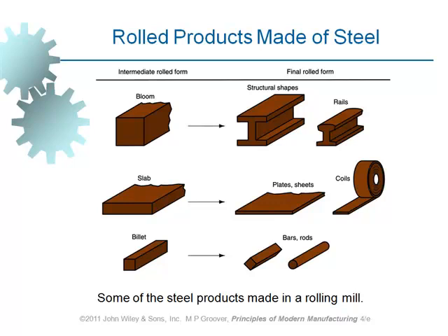At elevated temperature, we can alter the orientation of the grains which are random in the material. When material is being subjected to hot working, still we can alter the orientation, and as a consequence, we can achieve a better set of properties, a stronger material, a more desirable material. So even hot working does improve the properties of the material, and also cold working.